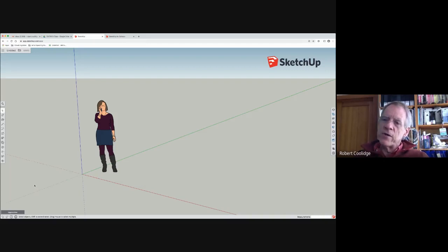In any one of those, if you type the actual units afterwards, imperial ones will accept metric and vice versa, if you're specific. With feet and inches, it'll assume inches unless you type feet. So that's, you saw me make the mistake. I forgot the character and I got 16 inches instead of feet.